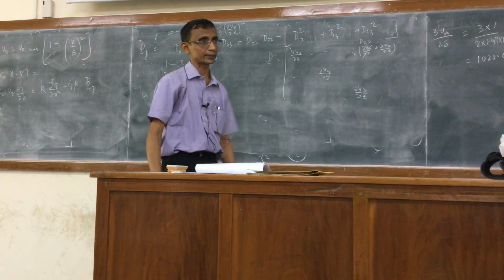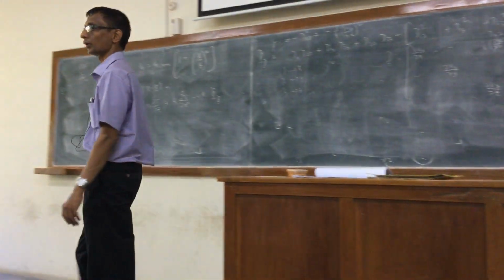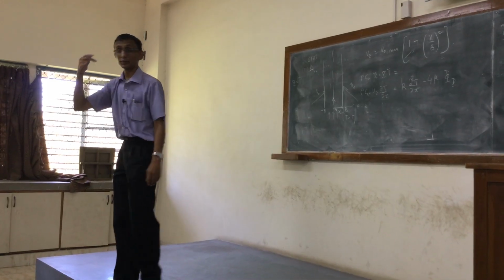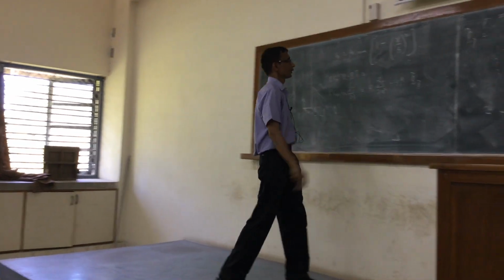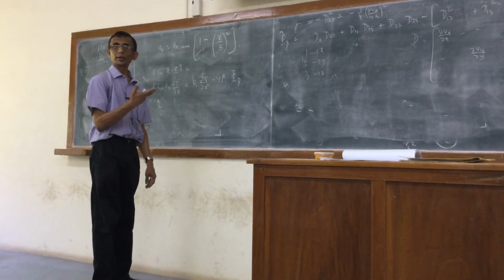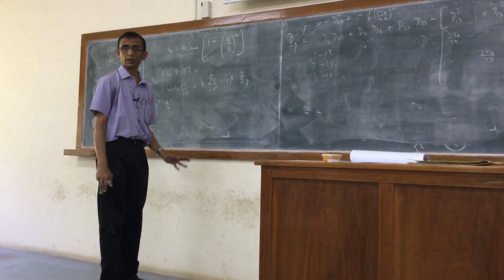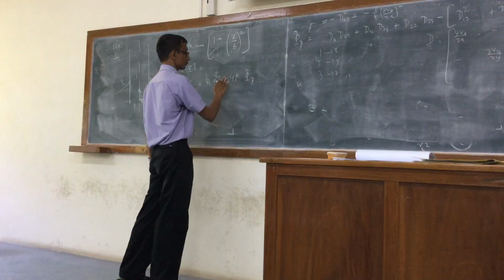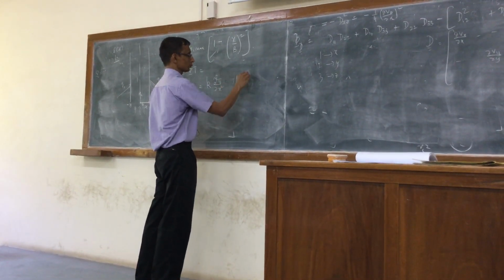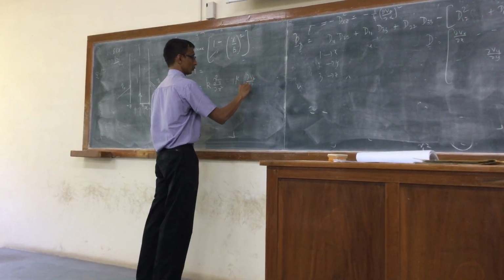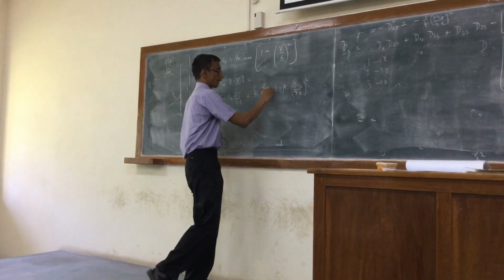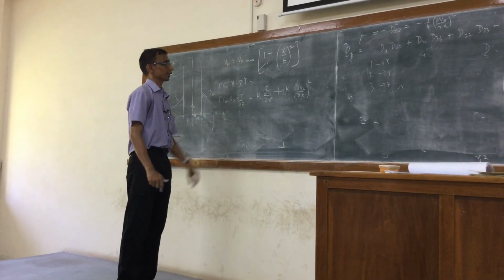It's almost looking like the case for the cylindrical tube. There also we have z, and z more or less matches with the z in the Cartesian. So there we had dvz by dr squared, and here we are getting dvz by dx squared. That's the only difference. Right? So clearly this would now be minus, and with the minus 4, that would be plus the whole square. This is very easy to estimate.